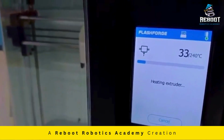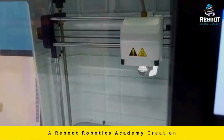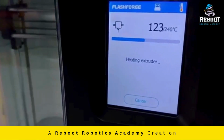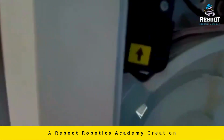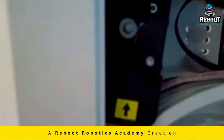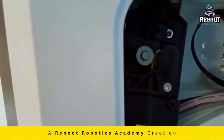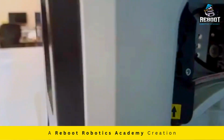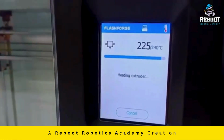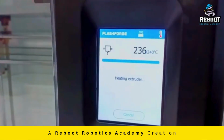As you can see, the extruder from which the printing material would come out is getting heated. Now we will be adding the thermoplastic material from this nozzle. This is the nozzle. We are just adding the thermoplastic material, and as you can see, it is going through this portion. Just after the heating is done, there will be an option showing that the extruder is totally heated, and then it will be able to take the new filament.